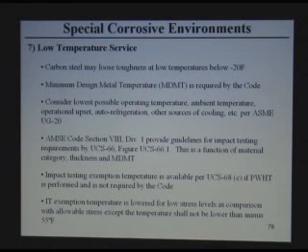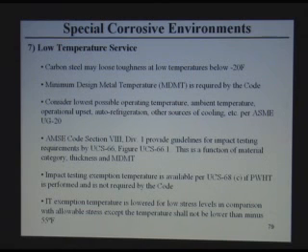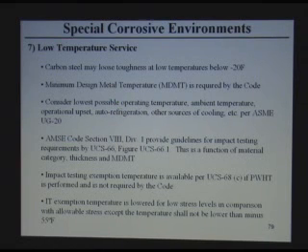The critical thing in this issue is to decide what the minimum design metal temperature is. It is decided based on operating conditions and ambient conditions. For example, if you are in Alaska or in northern Canada, the temperature is below minus 45 C or minus 50, so you have to design for that, because when you start up, you have low temperature unless you have some heat tracing or precaution to avoid starting up in cold conditions. You have to consider upset conditions, because sometimes upset conditions can create low temperatures. If you are not designed for these conditions, you might end up with cracking.